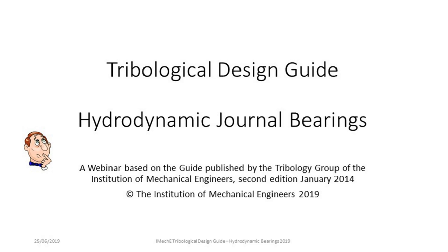Okay, so we've got a slightly more specific question here. It says, I'm currently simulating spiral groove bearings with deep grooves that do not allow for a wedge action to occur. Therefore, squeeze action is the only source of hydrodynamic pressure buildup. Is a pressure sustained in a lubricant due to squeeze action of around 30 megapascal small enough to neglect possible heating in the lubricant? Or are there other factors to consider, such as the eccentricity speed?